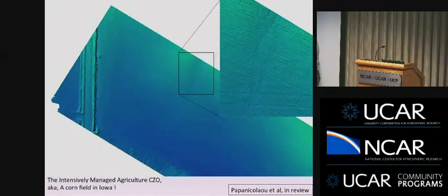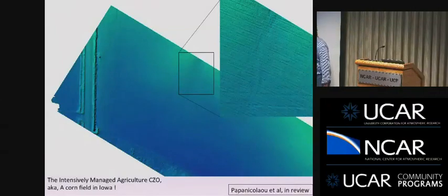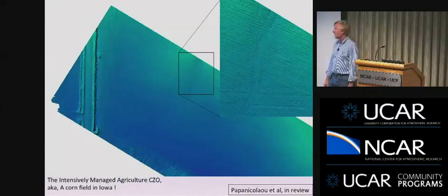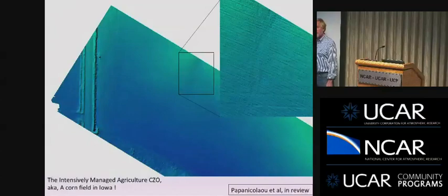And this drainage was essentially unobservable to anybody on the field. We're talking probably a centimeter of topographic difference. It's not even as deep as the wheel tracks here from the truck running over it. So from a series of 2 flights with a standard low-cost drone, we can now calculate the topography and produce these really high-resolution topographic maps. I think that's pretty cool.